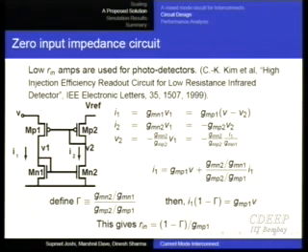What is really happening is that this transistor is acting as a PMOS source follower, and therefore driving the output with very low output impedance. Therefore it will force the voltage at this point to be fixed at whatever Vref is, because Vref minus Vtn minus root 2I by k will come here and the same drop will be here. So this will be a low impedance output driver, source follower like, which will force the output at that voltage. So this is the DC analysis.